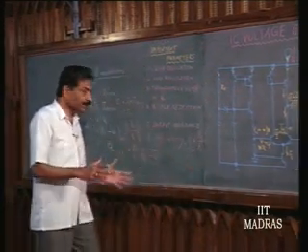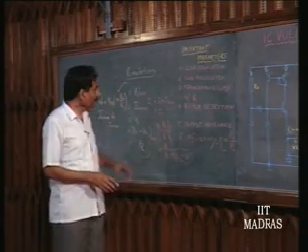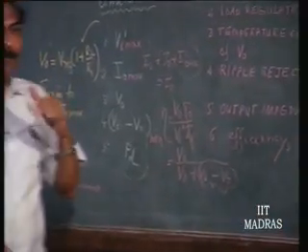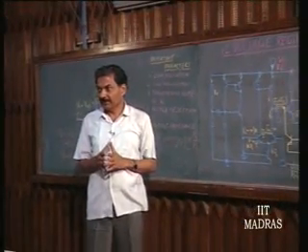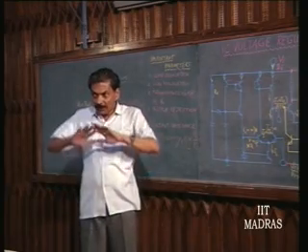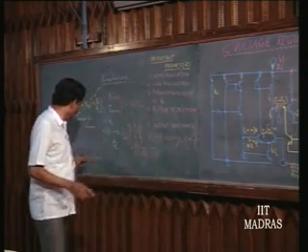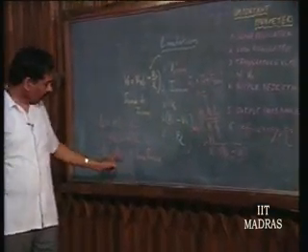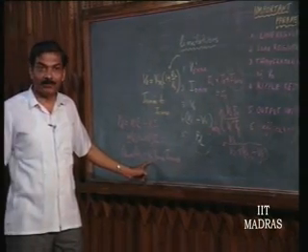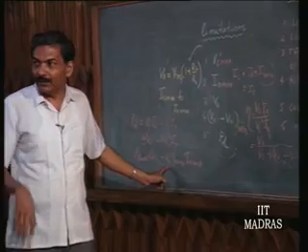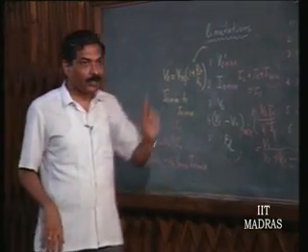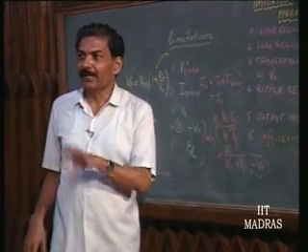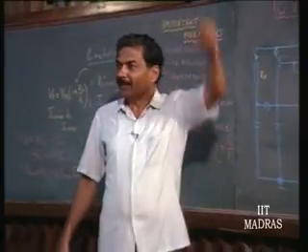Now, without the protection circuitry coming into picture, we know that Vi can keep on increasing now by itself. How much can Vi increase? Without going into power dissipation. With power dissipation we have come up with a Vi max. Have you understood that? And there you have to also perhaps bother about V naught minimum in a variable voltage regulator, right. That Vi max is known. Power is not at all demanded. What I am saying is it is not loaded. Now I am changing Vi.